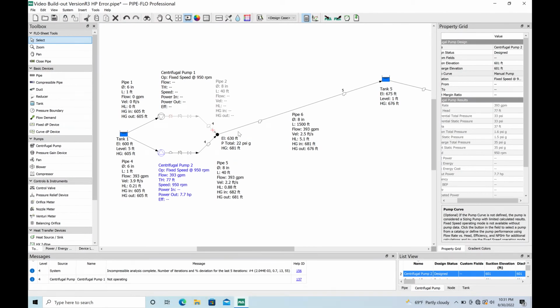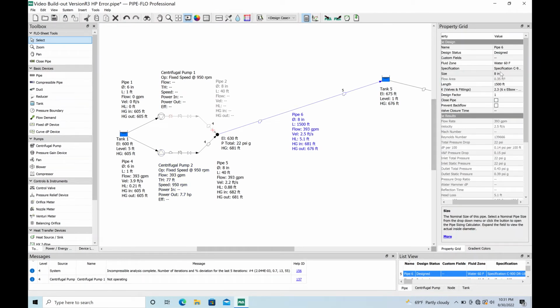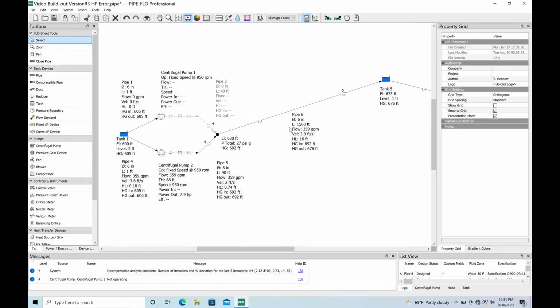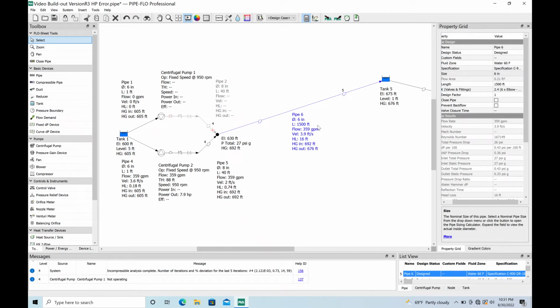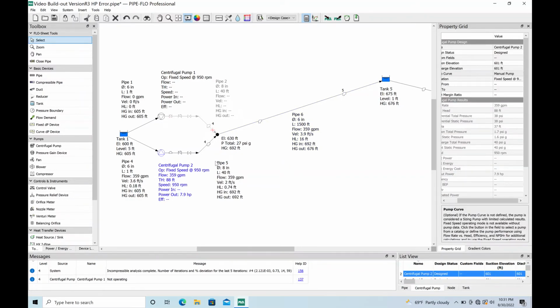Now, one more thing I wanted to show you, just to demonstrate what would happen to that system curve. As the engineer, you're designing these, so you have a lot of control over this aspect. Let's say that this pipe here that was 8-inch, for some reason it's getting plugged up. Somebody's pushing a lot of flushable wipes down on us. A lot of debris or grease or something is plugging up this force main here, and so now it's operating like a 6-inch pipe for some reason. So now you can see the velocity has changed from before, but we've gone down to 360 gallons a minute at now 88 feet. So that probably makes sense to you, I think.